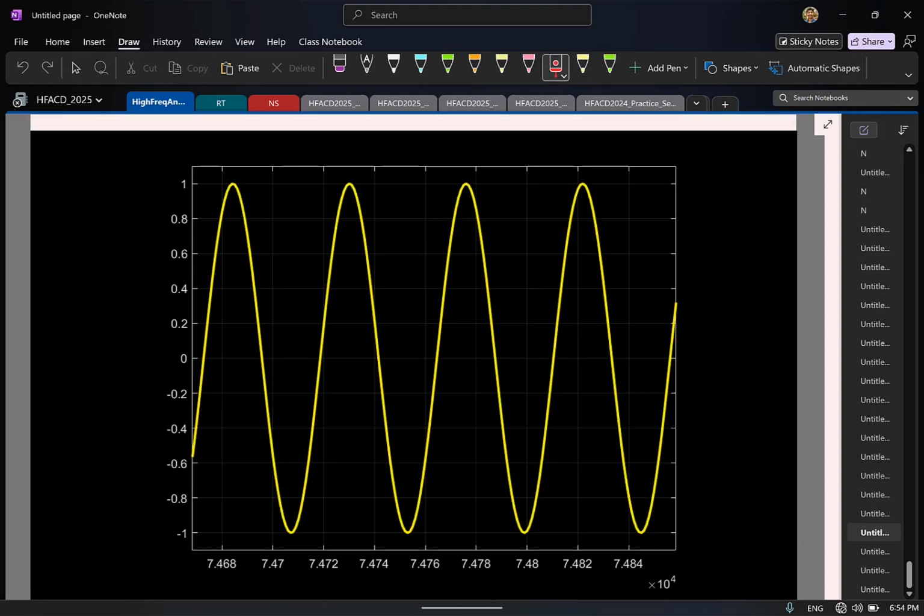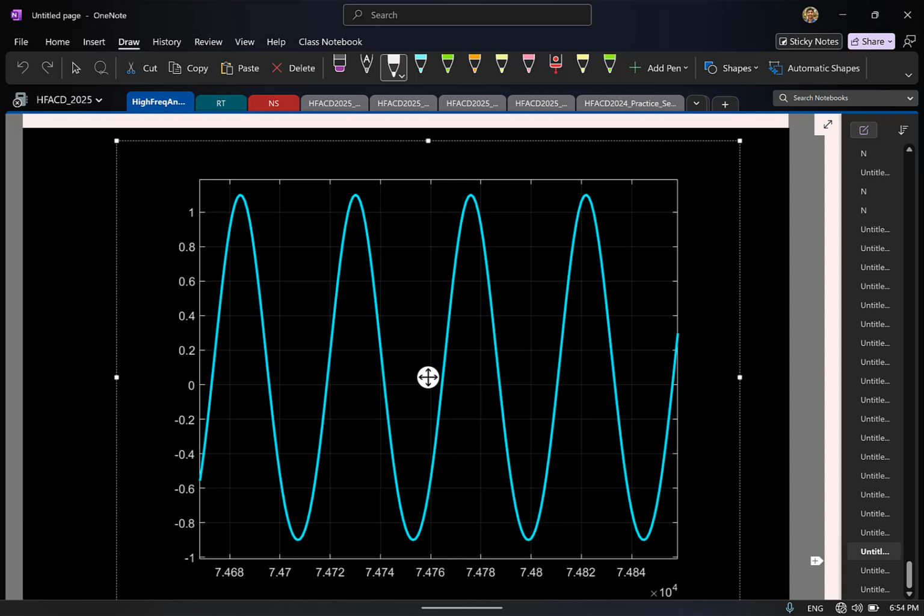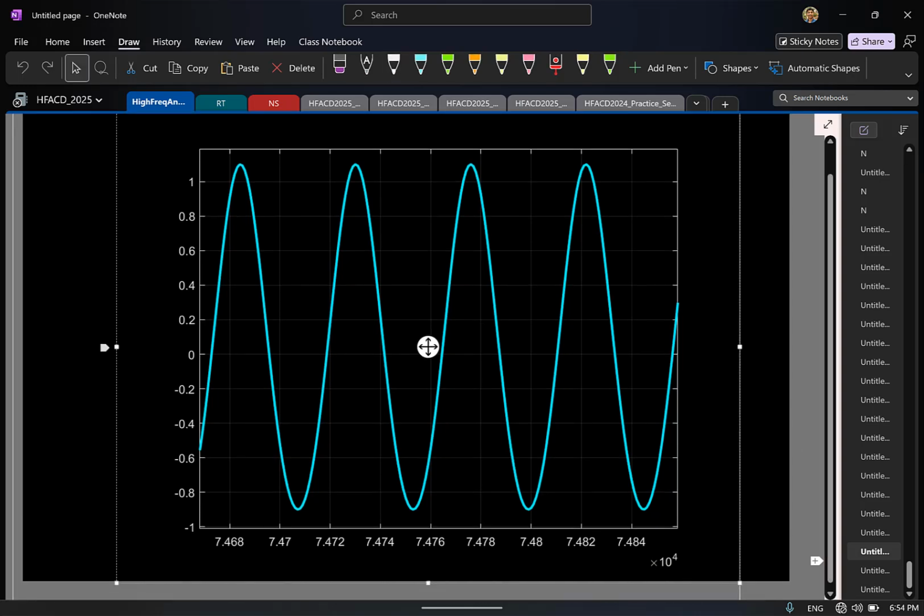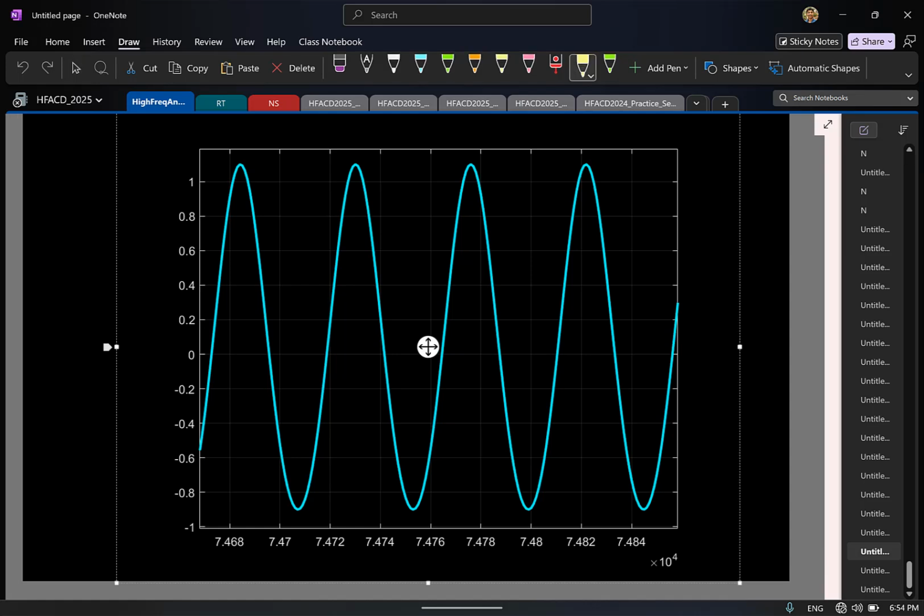Here I am showing the pure sinusoid, 1046 hertz. It looks like a sinusoid. It is a sinusoid. Next I will show the waveform after I added the distortion. That's how it looks. So bottom line, it is almost always impossible to see whether the waveform is distorted just by looking at the time domain waveform, because the usual understanding students have is that if it's distorted, it gets clipped like this.